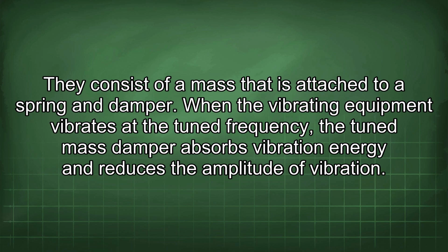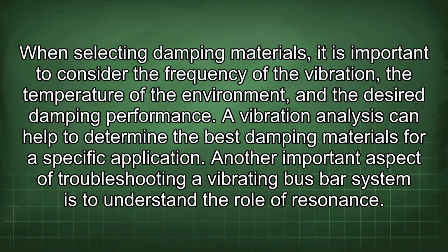When selecting damping materials, it is important to consider the frequency of the vibration, the temperature of the environment, and the desired damping performance. A vibration analysis can help to determine the best damping materials for a specific application.